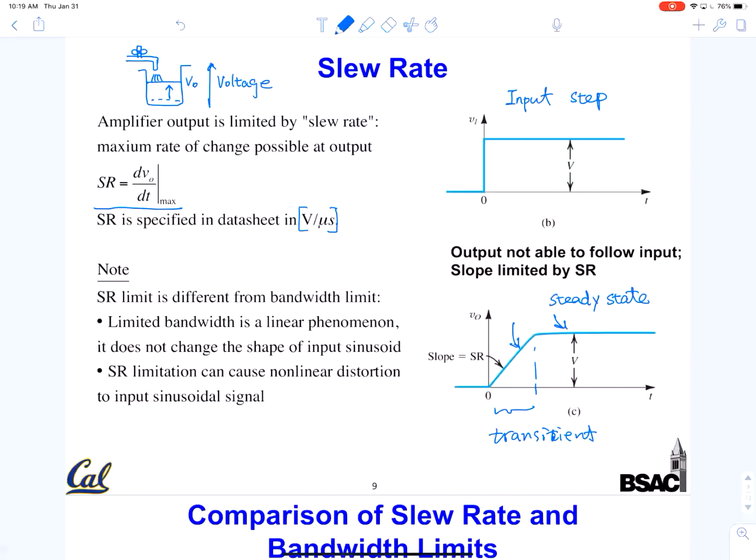But if you are designing the op-amp, that is a good question. If you go on to 140, you'll be designing a full op-amp, then yes, you have to choose your transistors. You have to choose your transistors at the output stage to be really fat and big, so they have large drive capability.